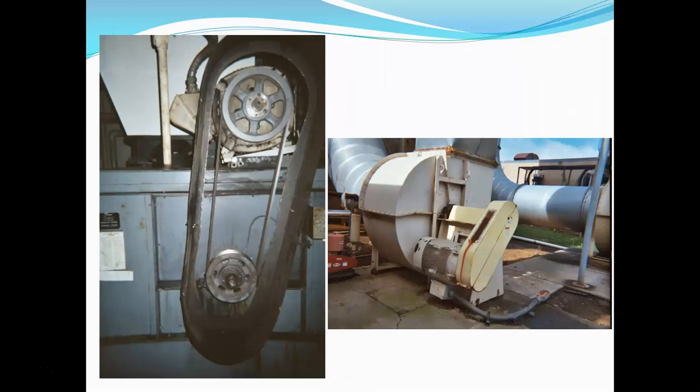Here are also applications of motors driving blower fans, but I have these slides here really to show the guard application, how a guard needs to be across the belt at all times when it's in operation. So you would only take the guard off when the motor is locked out and tagged out. The one on the left has just a face cover to go over the guard. You can have access into the belt, check tension, or replace the belt or sheave.